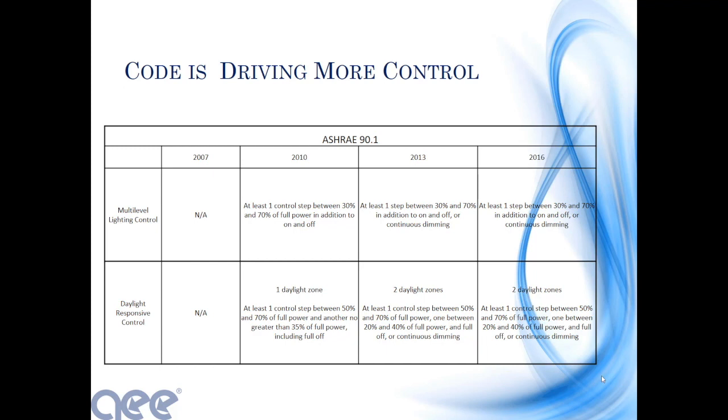Okay. Well, there's a couple of things that go into play there. We are going to get additional savings with dimming. All right. John showed the dimming curve where basically every 10% that you reduce the light output, you reduce your energy by 10%. Then you add in the perceived light level where if you want to have 50% perceived light, you're actually at 32% output.